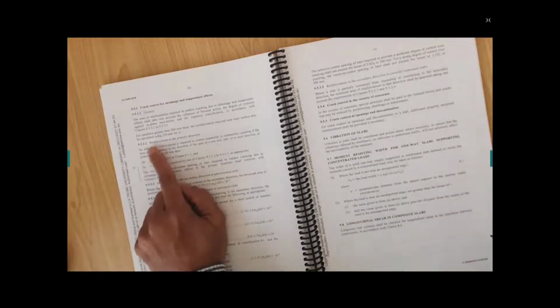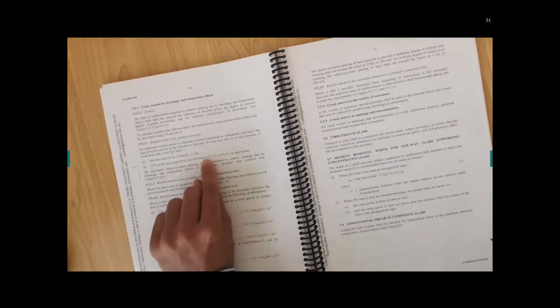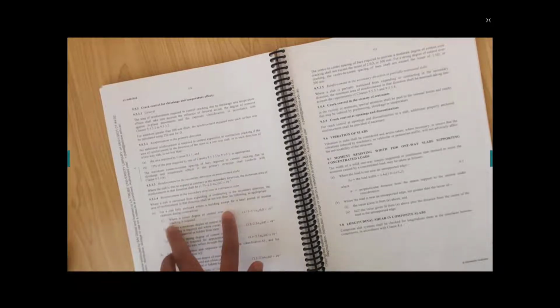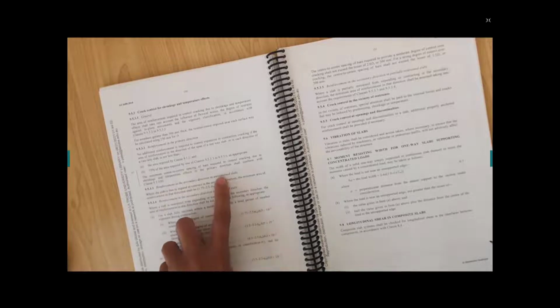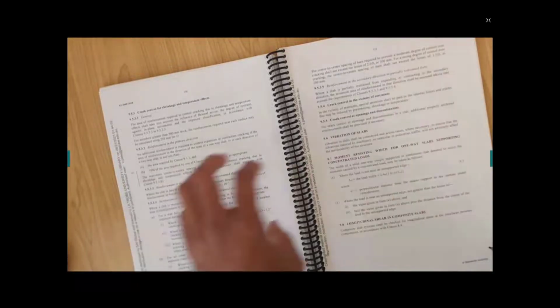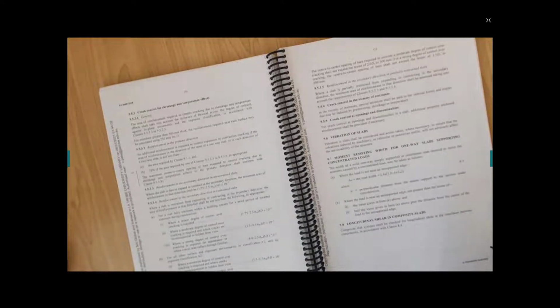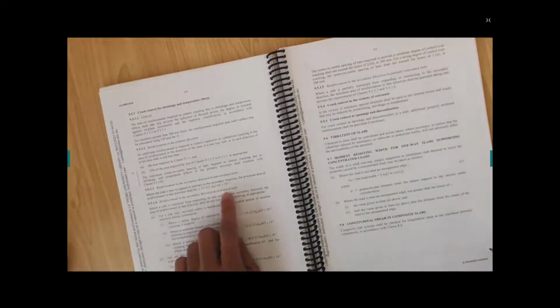In that case they said that for reinforcement in the primary direction you need to provide 75% of the area required by one of these clauses. So you need to come to the secondary clause 9.5.3.3 on restrained slab and partially restrained slab. There are three clauses given. Generally we have a restrained slab. Is it given in the question?